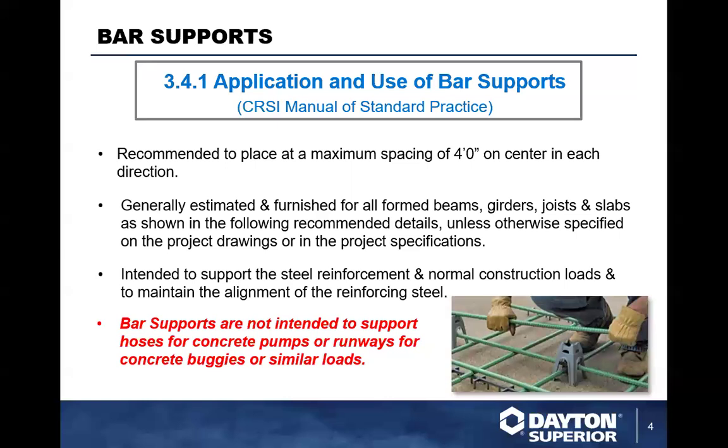And remember, the concrete is always going to crack. The steel reinforcement is there primarily to help limit those cracks and actually reinforce the concrete itself. Bar supports are not intended to support hoses for concrete pumps, runways for concrete buggies, or other similar loads. The bar support is designed to carry man load and concrete and the rebar. Not designed to carry all the other items here.